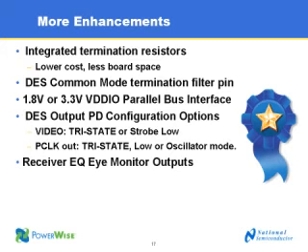The deserializer outputs have some configuration options. This is some feedback that we got from customers that they like to be able to have the deserializer outputs in different states when in a power down condition. So we've added some configuration. So the video outputs, that's the RGB, can be either tri-state or low when the power down is asserted. And the P clock can be tri-state or low, as well as you have the option to run off of an internal oscillator, so a clock output will always be provided regardless of whether there's an input. So that actually allows people to support different, say, system designs, right? That's right, yeah. And in some cases, the downstream devices need to have a continuous clock, so that provides a continuous clock to the display.